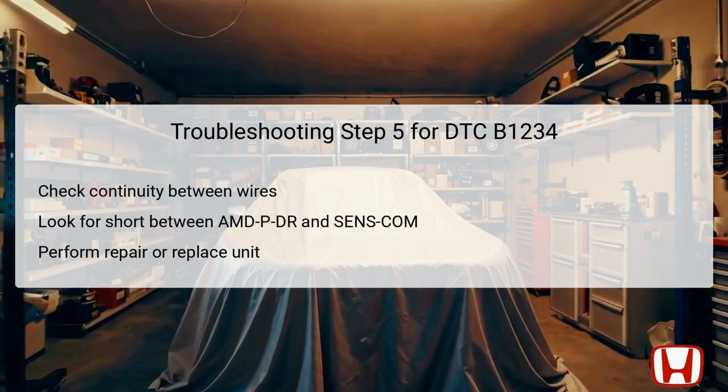This troubleshooting step requires the technician to measure continuity between the AMD PDR wire and the SensCom wire, while both the climate control unit and air mix control motor connectors remain disconnected. With the vehicle still in the off lock mode, this evaluation pinpoints any potential short condition between these two lines. If continuity is detected, it indicates a short that necessitates repair between the wires mentioned. If no continuity is present, it suggests that the climate control unit itself may be defective, prompting replacement.